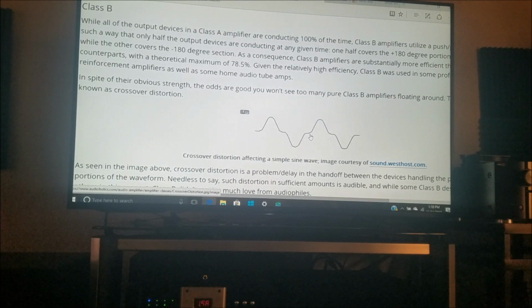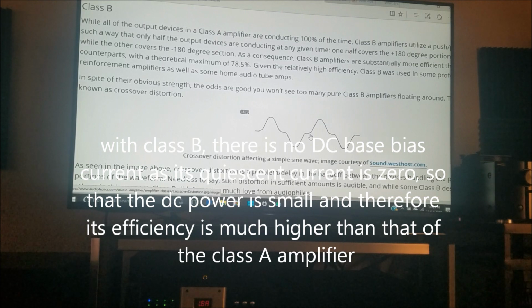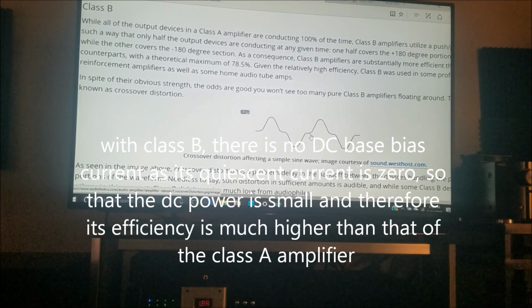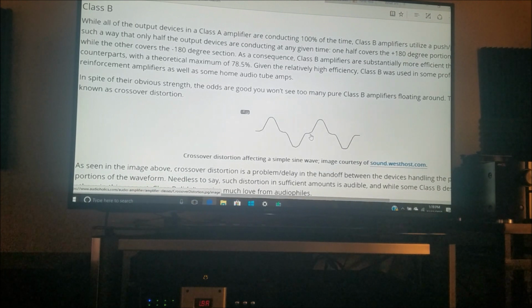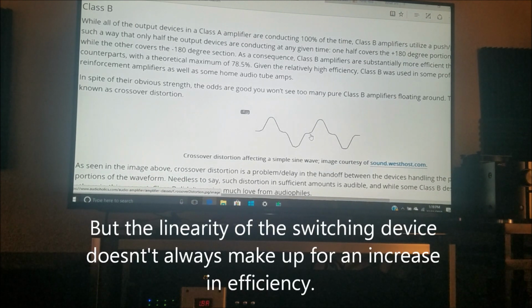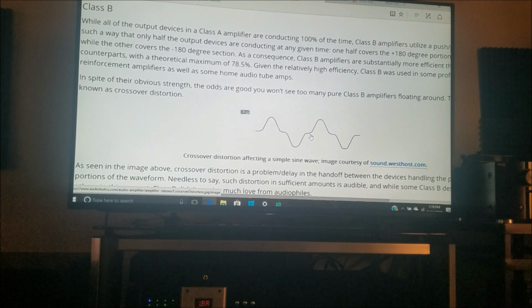In power amplifiers, it wastes power and limits the operation, increases the costs, and requires higher rated output devices. In a Class A amplifier, if high output power is needed, the power supply and heat become extreme. For every watt delivered to the load, the amp, at best, uses an extra watt. So for high power amps, this means expensive power supplies and extremely large heat sinks.